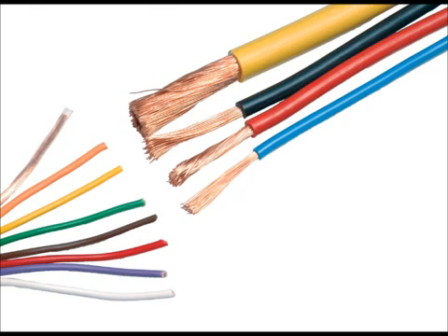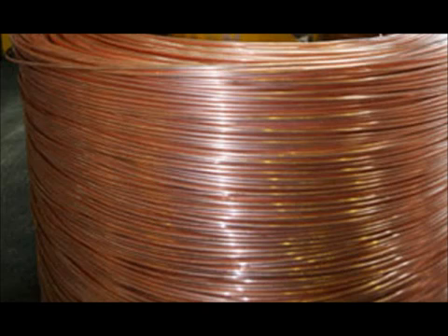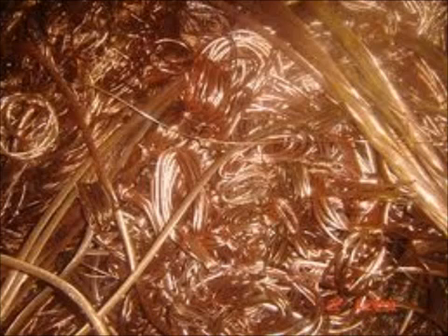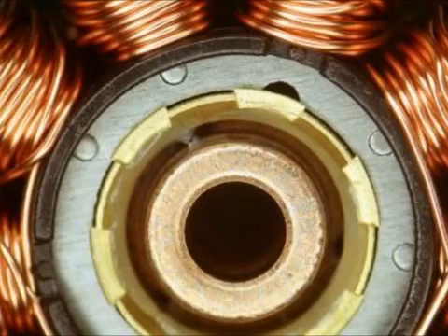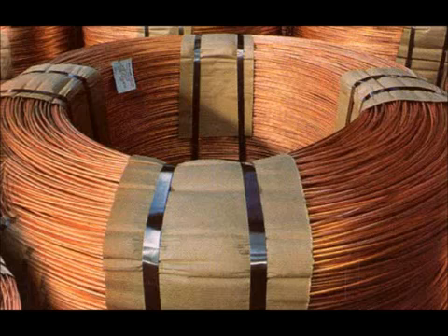So why copper? There's a list of beneficial properties copper possesses, such as high electrical conductivity, tensile strength, ductility, creep resistance, corrosion resistance, thermal conductivity, and the list goes on. So basically, materials with more beneficial properties than copper aren't cheap, while materials cheaper than copper don't have much beneficial properties. That's why copper is the dominant material used in electrical wiring.